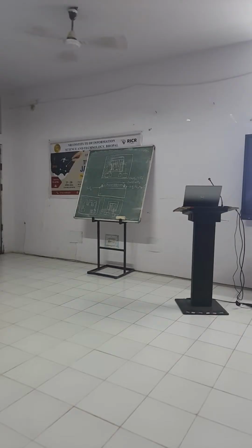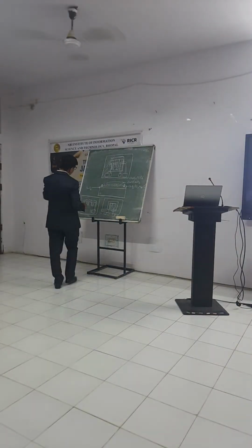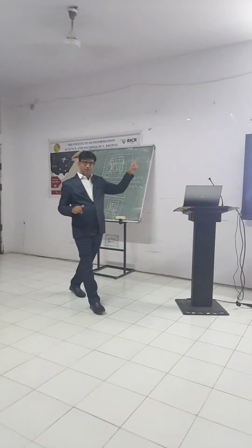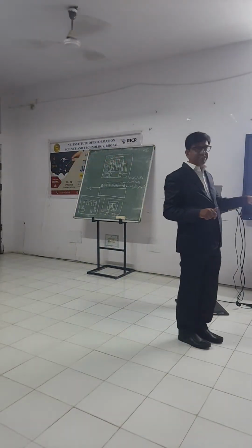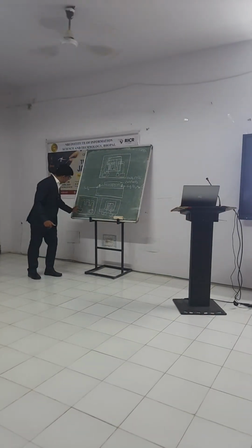Yeah, very good answer. How do you make a contact for your heater? If you cover your heater bed with oxide layer, then how can you make a contact? So we need to open a window for my heater contact. So I will deposit oxide over the wafer and, with the help of lithography, use the same step and open only this window, this window and this window.